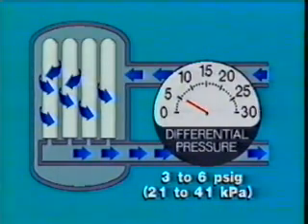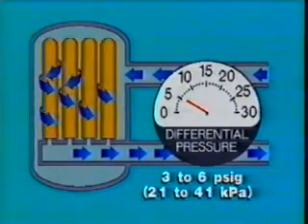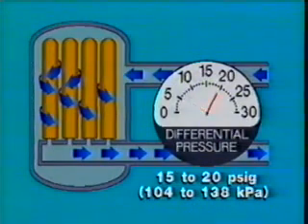The pressure drop increases as the elements remove solid material and eventually become plugged. When the pressure differential becomes 15 to 20 psig, the elements should be replaced to prevent stoppage of the glycol flow and possible collapse of the elements.